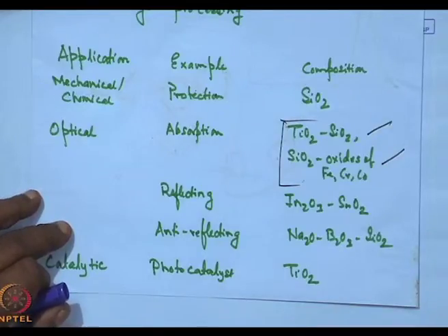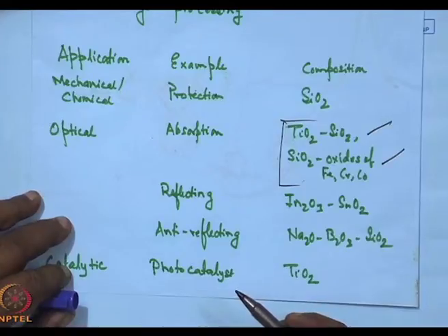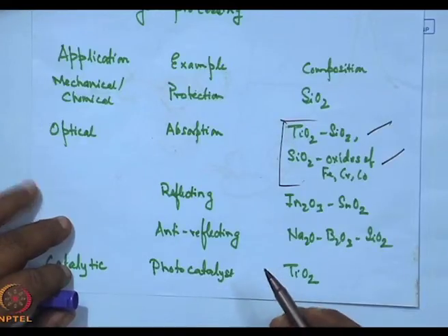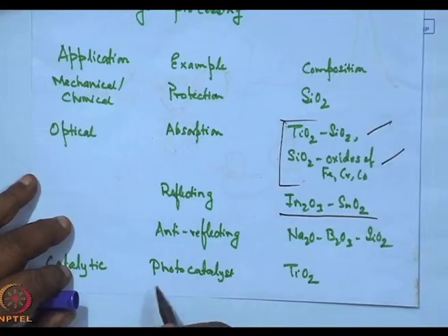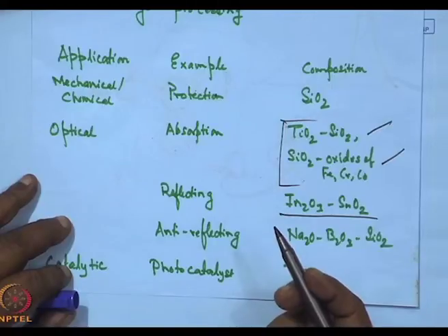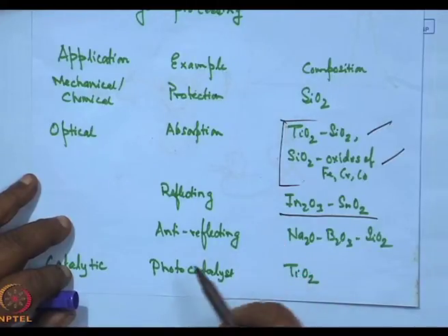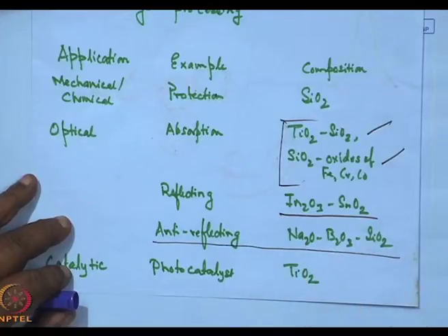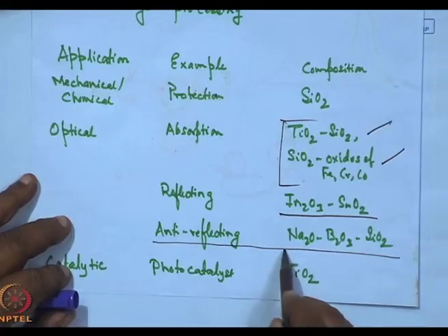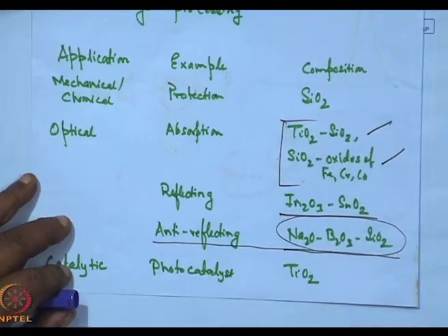Whereas in our place, if we want a reflecting coating, where I do not want the light or the heat to come through, indium oxide, tin oxide coatings by alkoxide based sol gel are now routinely available. If you are looking at anti-reflection coatings, since you have frequently faced reflection problems, these materials are already available in the market.